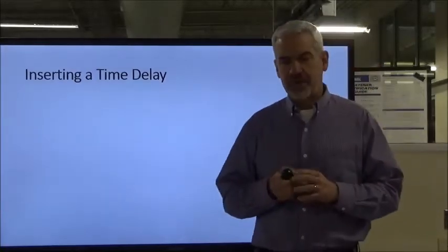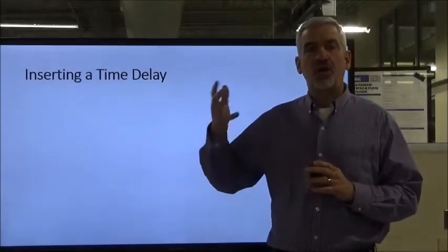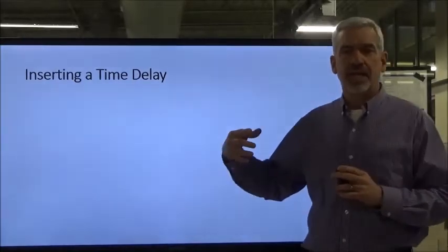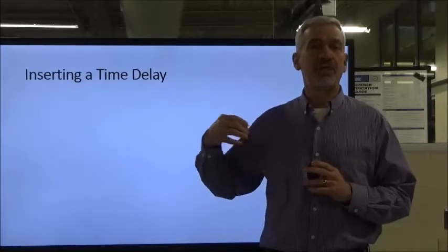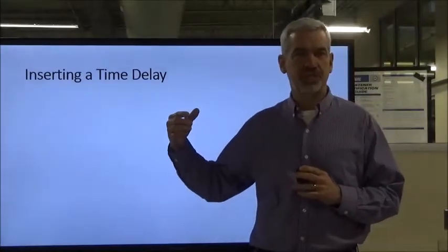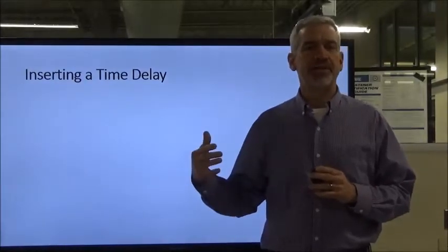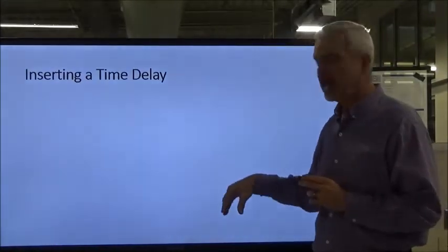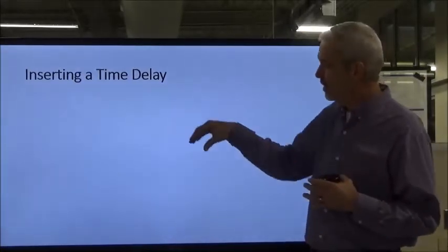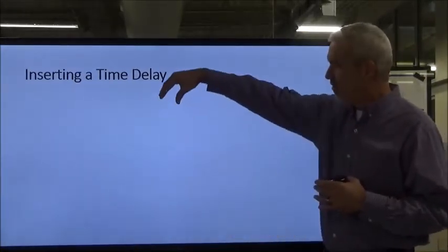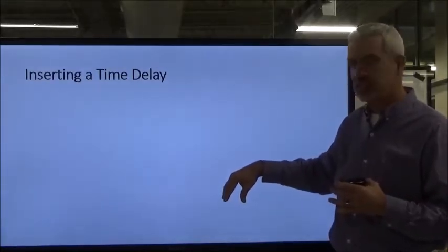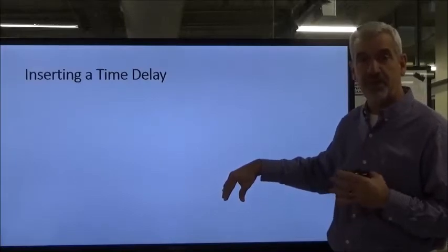So far we've set up our program first, and we gave it a title. Then we called another program and nested it into our program so it would execute a home position for us. Then we put in that first line of instructions, so it would go over the top of a wire nut. Right now, in your imagination, the wire nut's sitting about right here, and we have gone from home position to an air point, an air move right there, just hovering over the top of it, and we've come to a standstill.